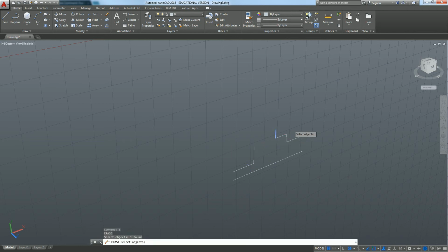So the good thing about real-time recording is you get to see when I make mistakes how I go through and fix the mistakes. So this line segment is too long. I've got a diameter of 0.5 that is going to a diameter of 1, so that line segment should only be 0.25. So we'll come in here and we'll put in our 0.25. That looks a lot better.